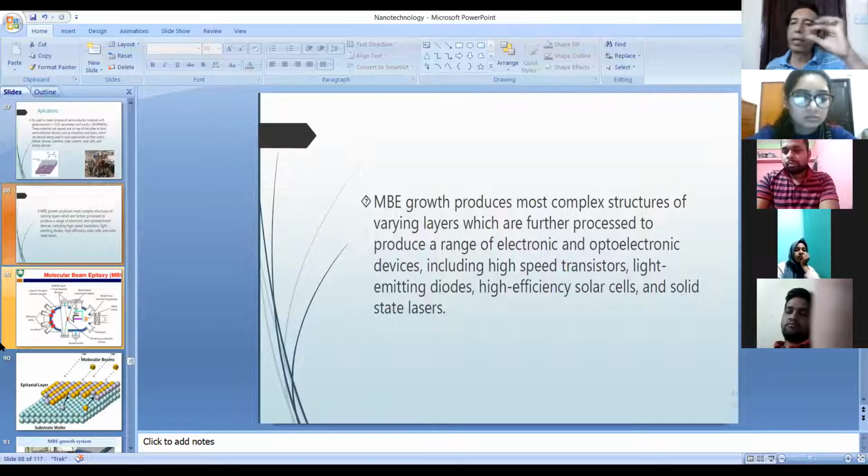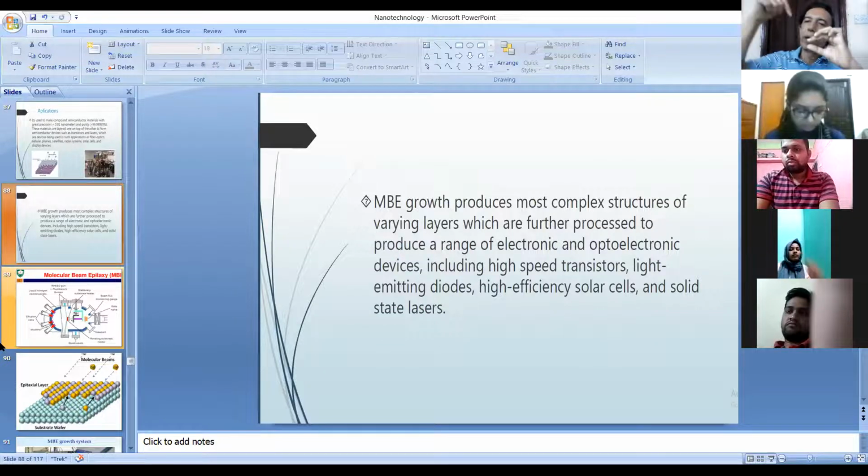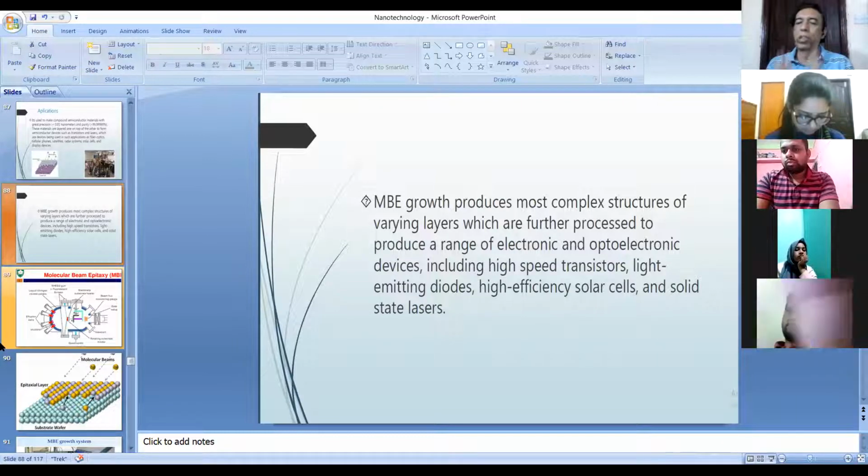Then you make a thin film on the substrate and dope p-type on that thin film. So for different types of doping also, you can prepare a thin film of the same substance as the substrate. So this is the first use of homoepitaxial growth.